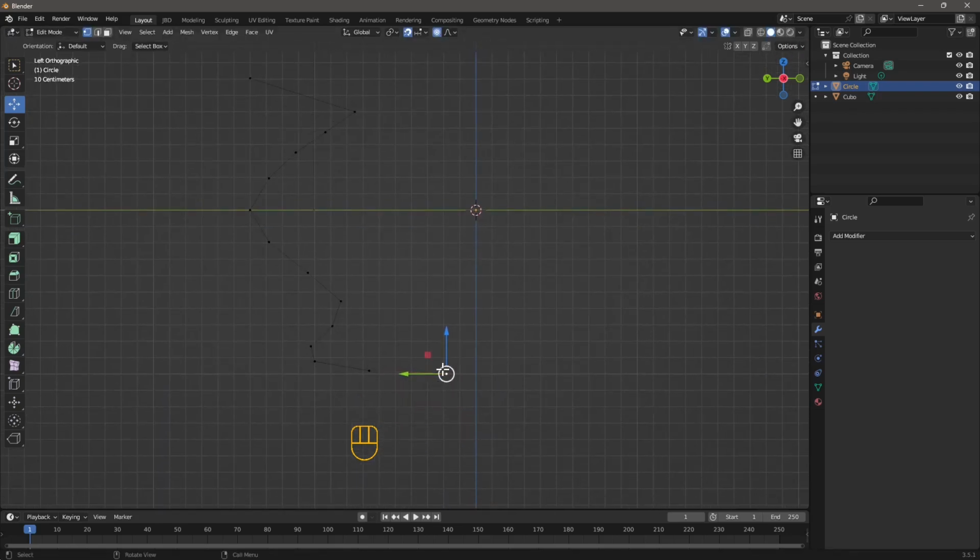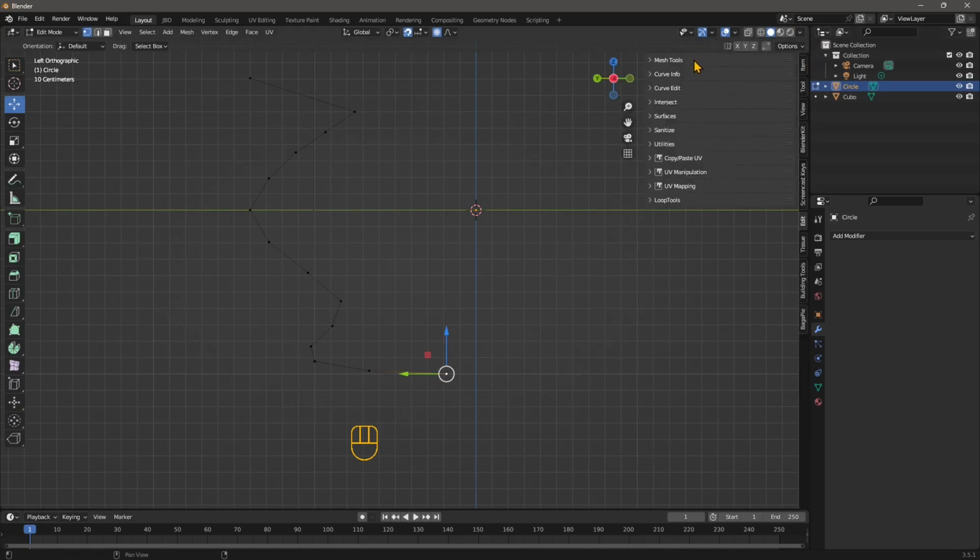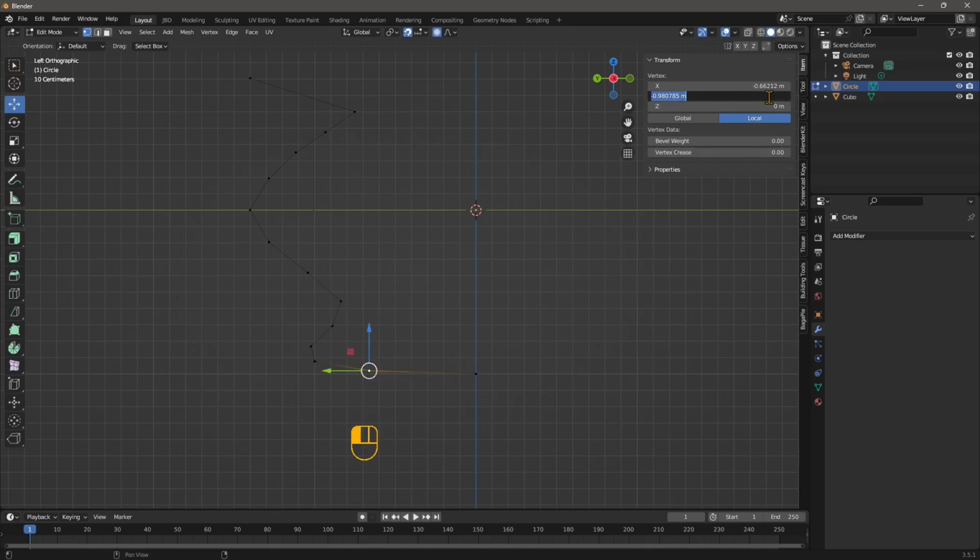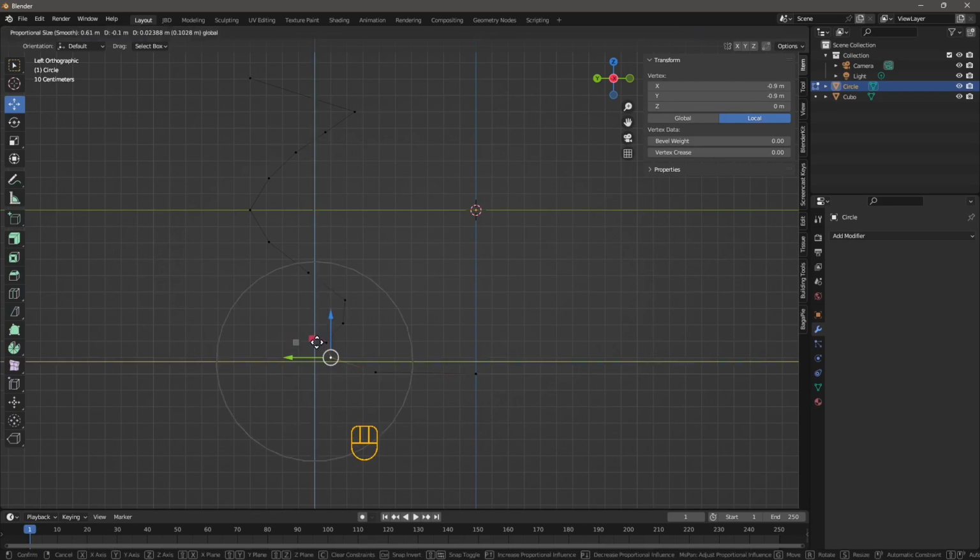And here you can adjust the height of the item, which is the vertex right here. So if it's not okay, if you want to place it perfectly in one position, you can use the values. So I want this perfectly at 0, and this is going to be -1 epsilon and z 0. And also here I want it to be perfectly at -1, so this is going to be like a straight line, and so it's going to have like a perfectly flat base.